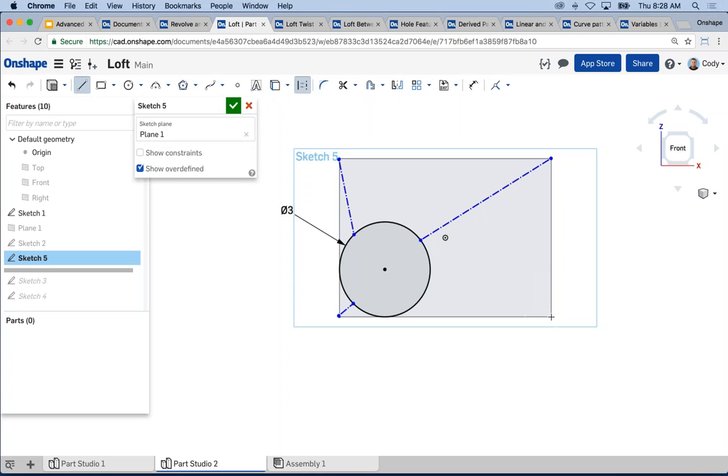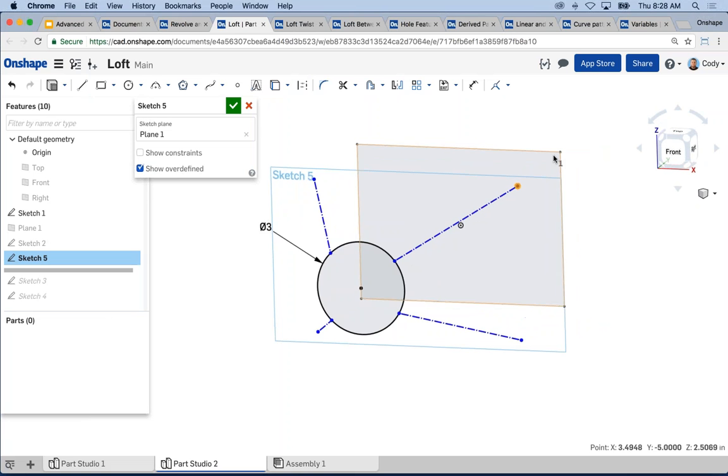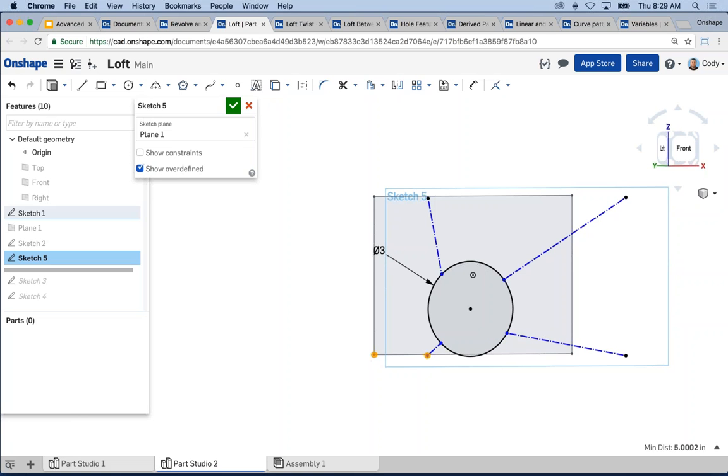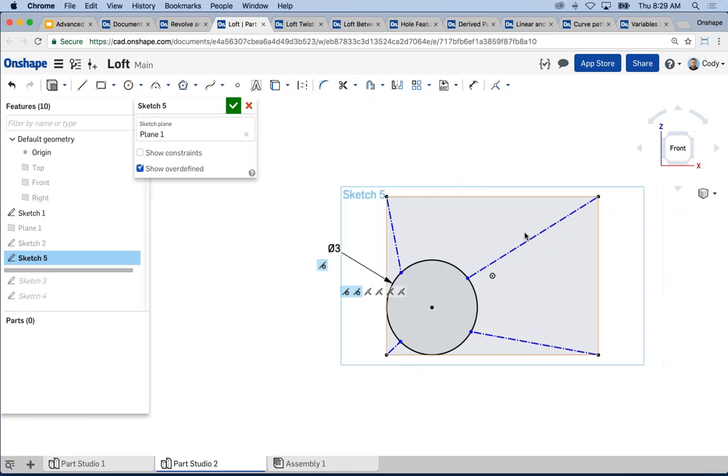But what I generally do in something like this is I would construct some kind of construction lines that give me some kind of gauge to the shape behind it, right? And I may even come in and constrain them, right? And maybe even add dimensions. It just depends on the time. Again, I'm just going to try and fly through things here. But constrain it to all 4 corners, maybe come in and add my dimensions.